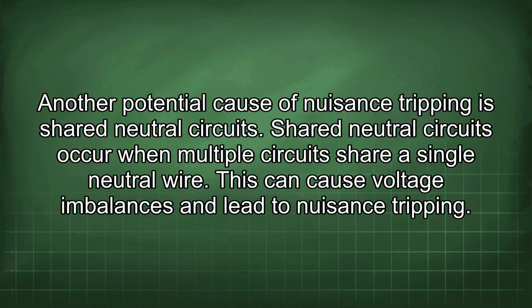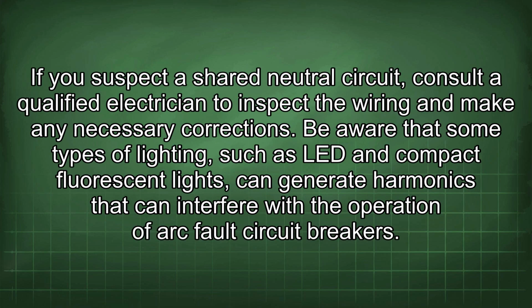Another potential cause of nuisance tripping is shared neutral circuits. Shared neutral circuits occur when multiple circuits share a single neutral wire. This can cause voltage imbalances and lead to nuisance tripping. If you suspect a shared neutral circuit, consult a qualified electrician to inspect the wiring and make any necessary corrections.